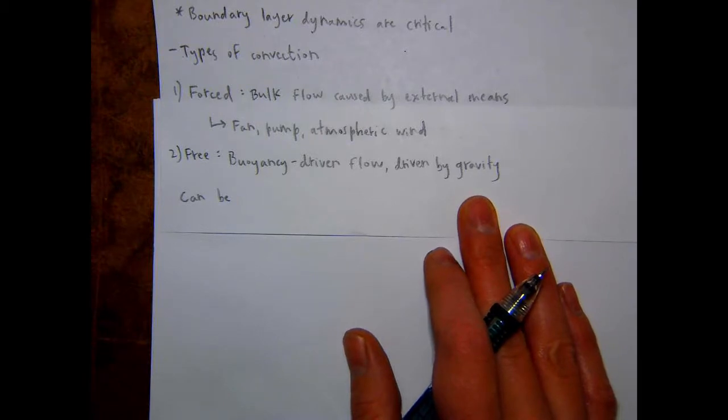Even if the atmosphere is at a different temperature, the flow that's surrounding the object is going to be warmer. So then the free convection wouldn't occur very quickly either because you still have a very small temperature difference. So you're not going to have very much warming via diffusion and then buoyancy either. Okay, does that answer your question?